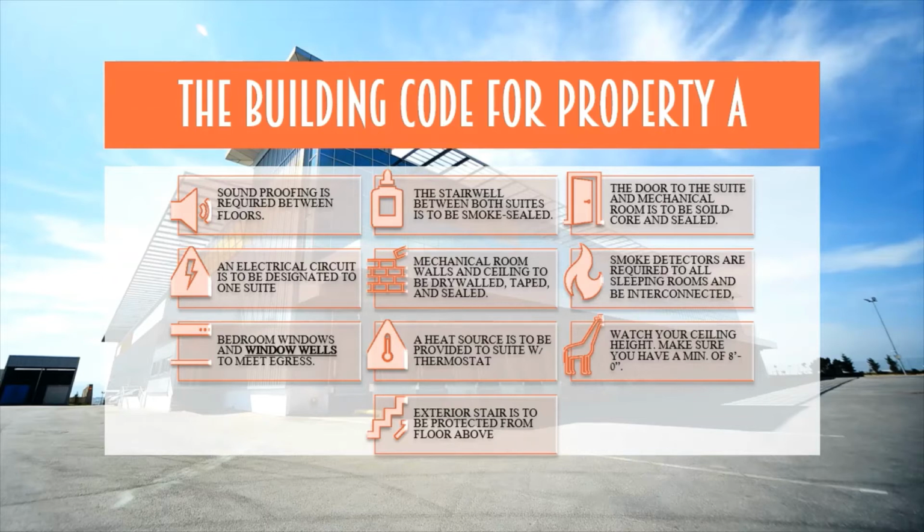For a brand new suite, I very much recommend that you have a sub panel that operates just for the suite. Or if you have an existing suite, you have to make sure that no circuit also controls the suite and anything else upstairs. You want to keep both the suite and upstairs completely separate.